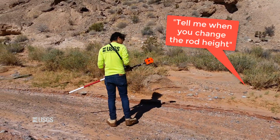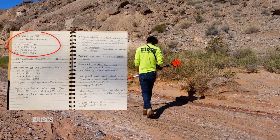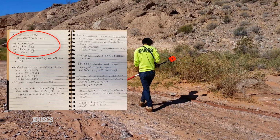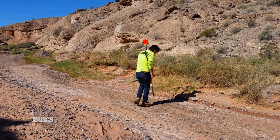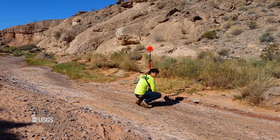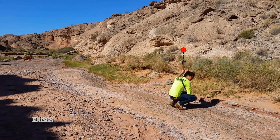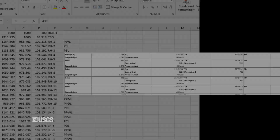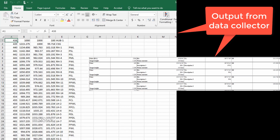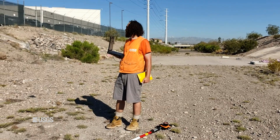Instruct your rod person to tell you if they change the height of the rod, and, this is important, write down every rod height change in your notes, just in case you forget to enter the change in your gun or data collector. Survey all the high water marks on both banks to the hundredth of a foot, making sure to record any rod height changes and the composition and quality of each mark if the flaggers didn't already do that for you. The rod person or other party member can help with this documentation. Your data collector will record the point names, northings, eastings, and elevations for you, but if you don't have a data collector, you will need to record these items as well. At this point, stop and take a break.